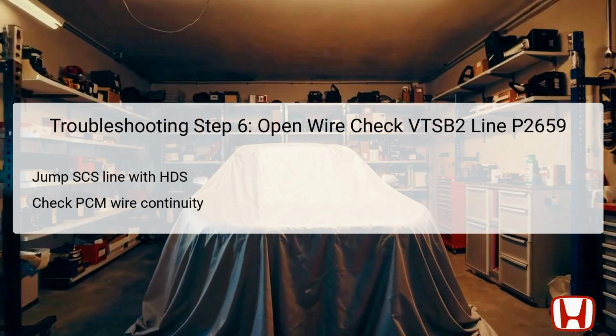more accurate continuity assessment. Continuity must then be checked between test points on the rocker arm oil control solenoid A and the PCM connector. A lack of continuity indicates that there is an open in the wiring between the PCM and the solenoid, which requires immediate repairs. On the other hand, if continuity is confirmed, the technician should review any service bulletins relevant to the DTC and consider substituting a known good PCM if troubleshooting indicates.